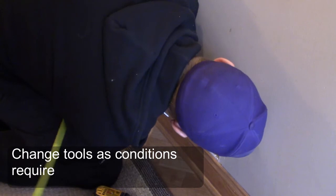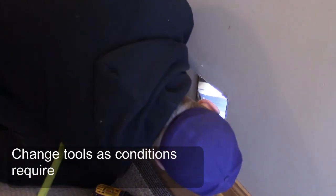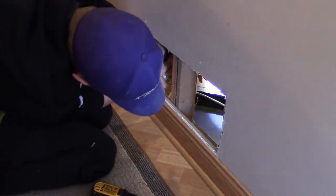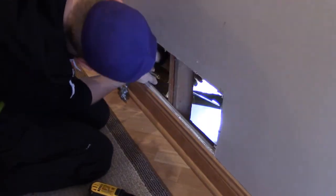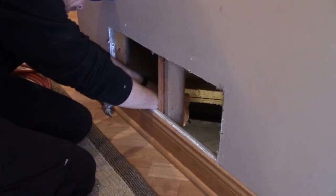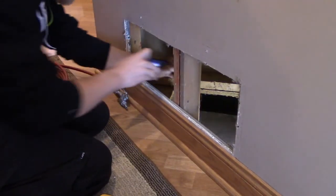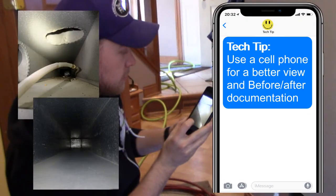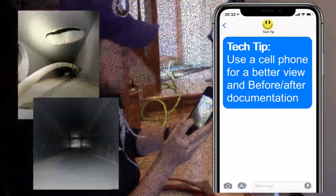As you continue cleaning, you may need to switch tools and conditions change. For example, the air wand may be needed near the main level near the trunk line. Here's another tech tip. Use a cell phone for a better view and before or after documentation.